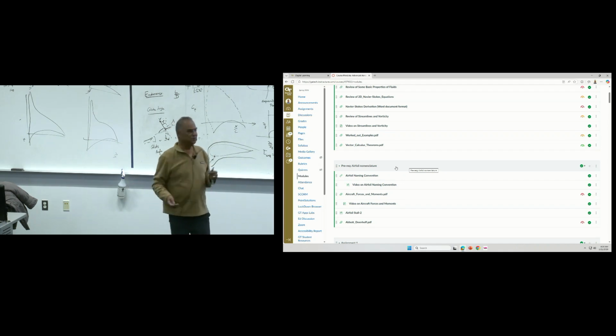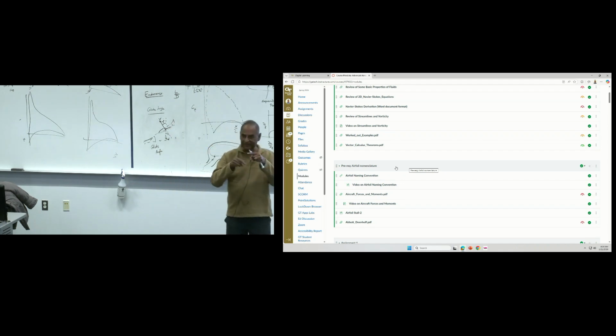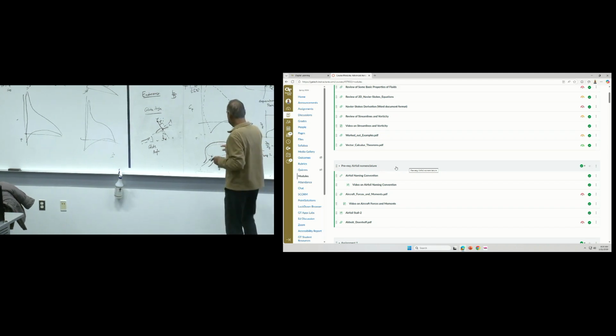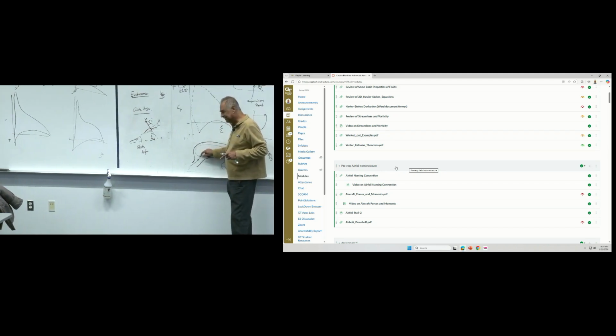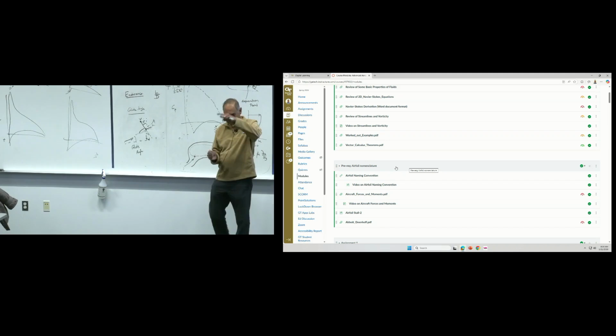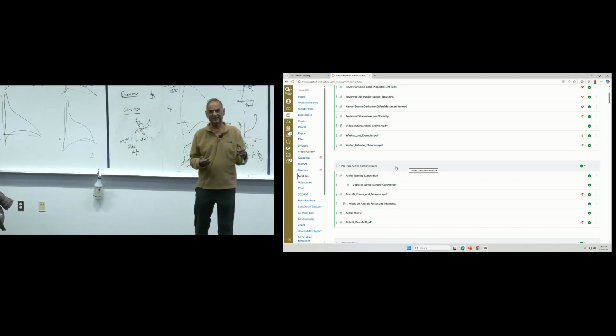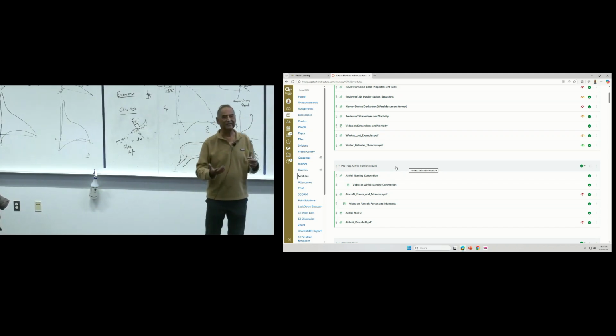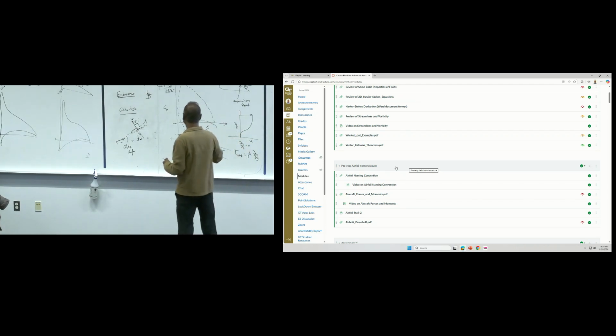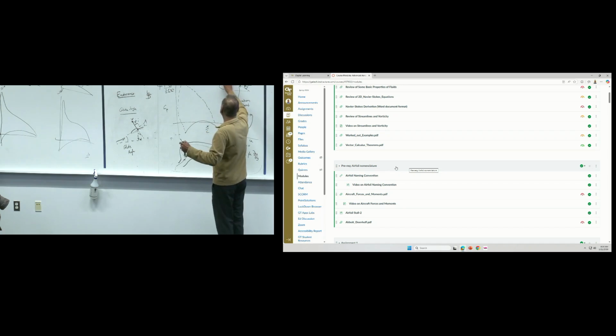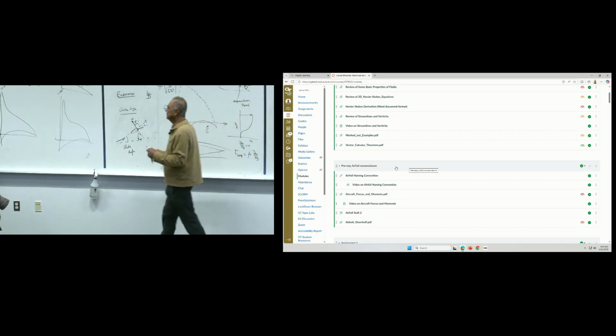Okay? So the Wright brothers tried to blunt the leading edge a little bit, but modern airfoils have a relatively large radius of curvature, rounded nose airfoils. They do better. They tend to have a trailing edge stall. Okay? So on the airfoil itself, there are a lot of interesting things going on. Transition to turbulence can occur. Trailing edge stall can occur.